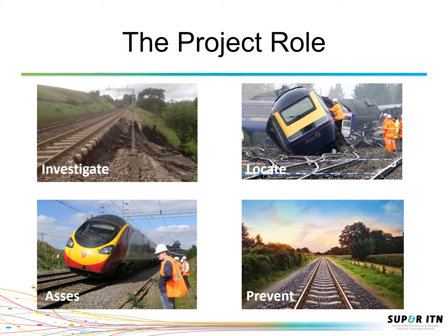Usually, these failures are a result of different degradations in the base of our track that is made of ballast beds, subballast and subgrade. The project is looking for a solution to help railway engineers to identify early signs of these degradations. We want to help them to locate on time weak spots along and across the railway track so the maintenance operations can be done where required.